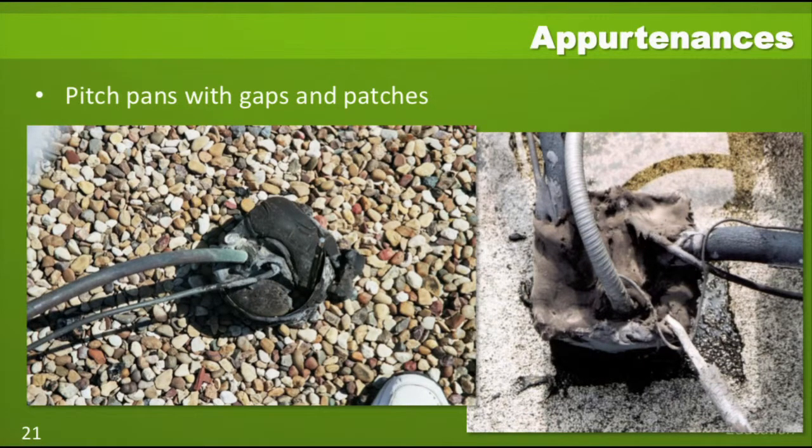Here we've got some examples of pitch pans we've seen on the roof, and you've probably seen them too, where you've got multiple lines coming in, you've got gaps and cracks in the pitch pan, and many possible sources for water infiltration.